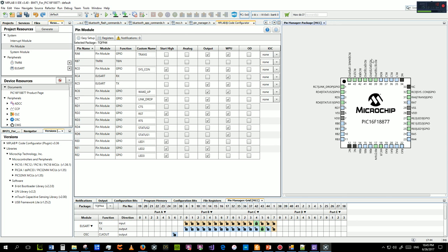Now you do need the reset pin. I highly recommend putting the reset pin directly to your MCU, and do not put it to a push button, because every time you want to change something, you have to push that button. It'll get really frustrating. The CTS pin is not required on the initial programming. Really, I don't think it's required at all. If you want to use it, you can use it.